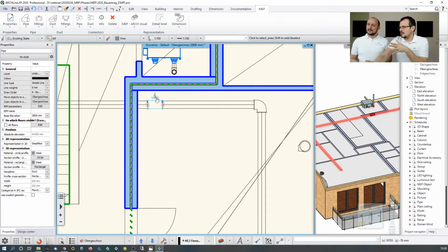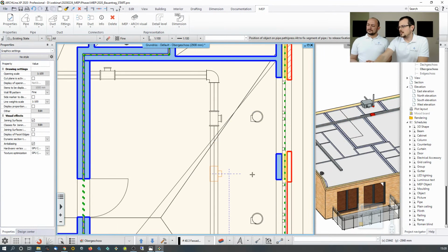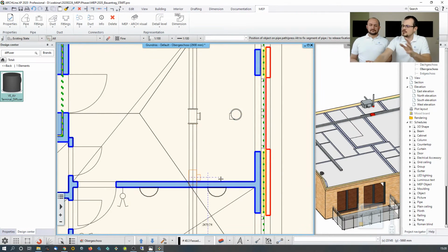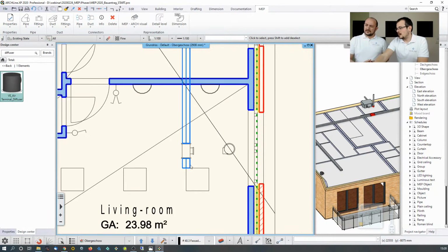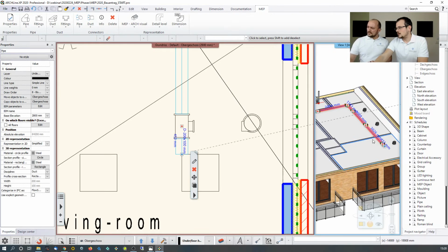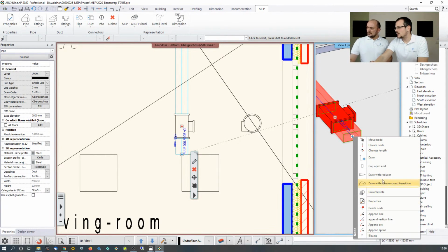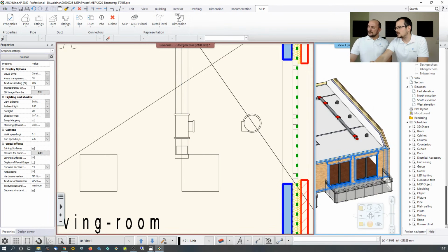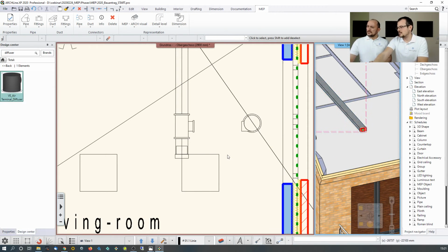Before I figure that one out, I'm just going to make a few copies and align them with the 3 vents over here. I'm not going to do it on the other side because that's just repetition. Actually, one thing that reminds me, I have to cap this off because it's an open end. That's the end of the system. I'm just going to do it in the 3D. Click on it. I'm going to cap the end over here, and the same thing here, just to make sure that I'm not forgetting. So it's a nice airtight system.